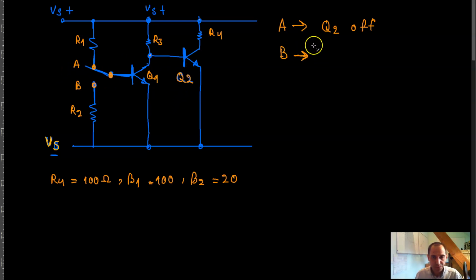So now if the switch is in position B, then the base of this transistor Q1 is tied to ground through this resistor. And there is a specific reason why. You might ask, why is there a resistor to the ground? This is some sort of design precaution that designers and engineers take to make sure that when this transistor is tied to ground, it's really tied to ground, and there is no way that any current can pass through to the base of this transistor.